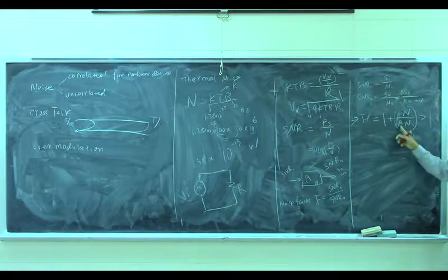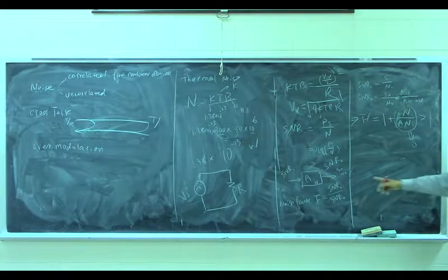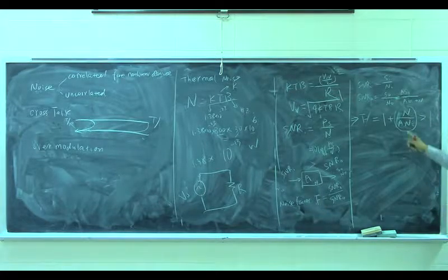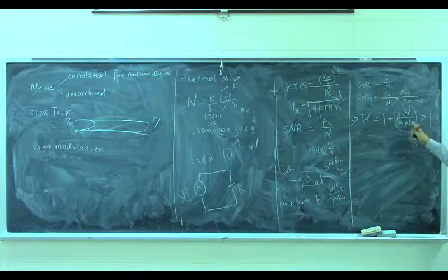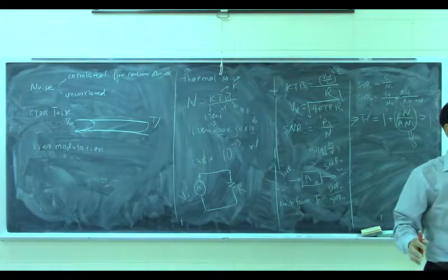Either way, you can make A equal to infinity, right? So the gain of your system equals infinity. Can you do that? Not easy, right? So there's no way. Input noise is always here. The other way is you can make your additive noise 0. That means your devices, like resistors and transistors, have no noise at all.